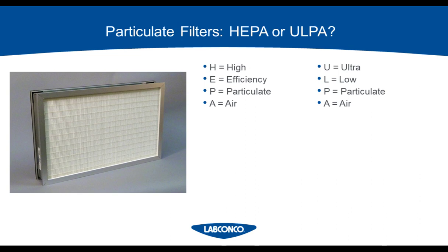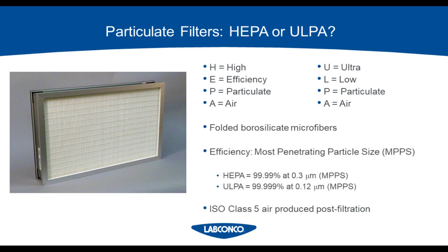Both of them are made of borosilicate glass fibers that are woven into a random weave and then folded into a filter that looks something like what you're seeing on the screen right now. Here you've got an aluminum frame that has a gasket on it, and then all of the filter media to trap all of those particles before they end up somewhere else in the lab or ductwork of your building.